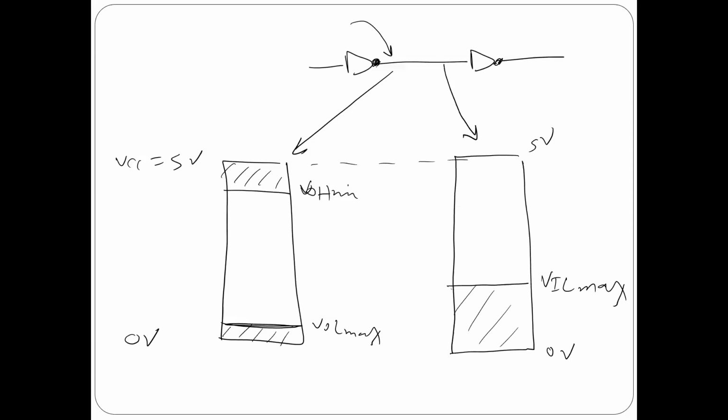You got what I'm saying? So if you want to input logic 0 here, you have to make sure the input voltage is in this range. You can see the output low maximum is already in this range, so it should be okay. It should work. It's compatible. When the first one outputs 0, the second one will take it as 0, because it is in this range.